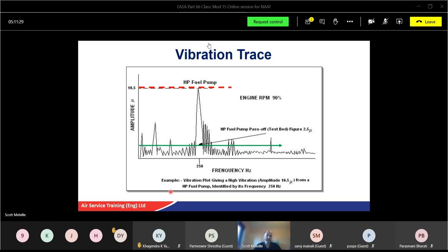Which type of flow meter would be used where high flow rates are to be measured? Helical vane flow meter. Just think of impeller on a boat. That's high flow rate. Okay, good.